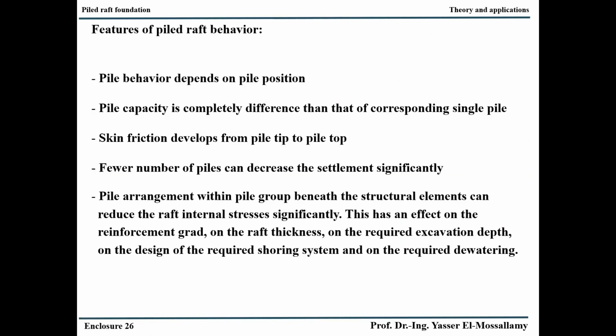Therefore, the main feature of the behavior of a wide raft foundation is that the pile performance will depend on the pile location. There is a difference between a pile in the middle, a pile at the edge, and a pile at the corner. Therefore, if I am a structural engineer and I would like to calculate the raft using structural software like SAP or SAFE, and I apply the same key value, the stiffness value, for all piles, I directly underestimate or overestimate the straining action of this raft.